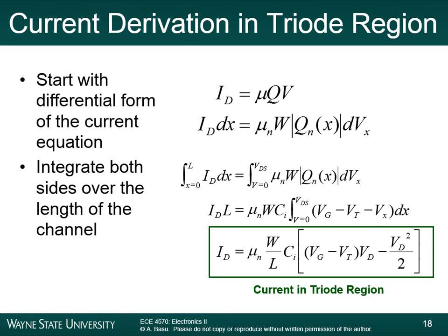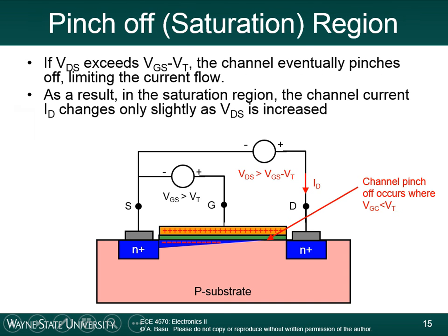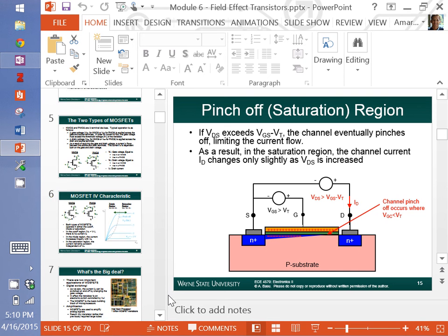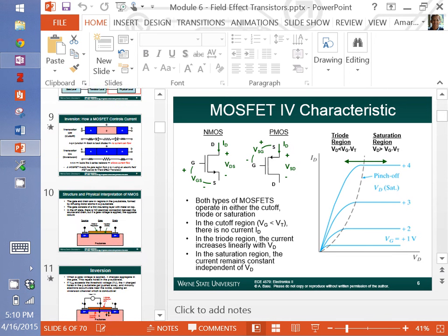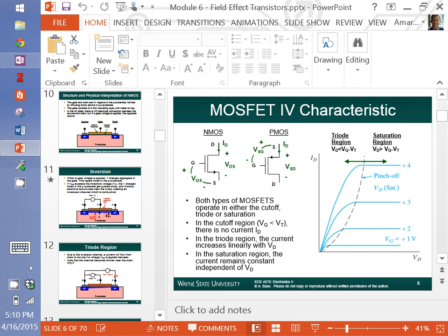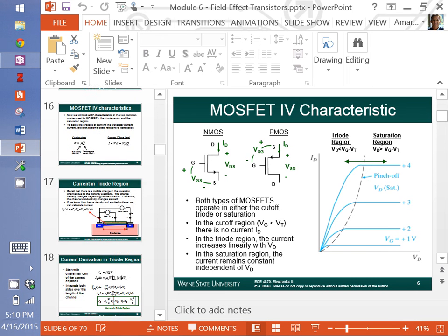All right, this equation describes the current in the triode region, just here like this. That equation describes the current in this triode region. Now, just conceptually speaking, it looks like an inverse parabola. This part starts to look like an upside down parabola, and this part here looks like a linear function, a line. So where does that come from in the formula?